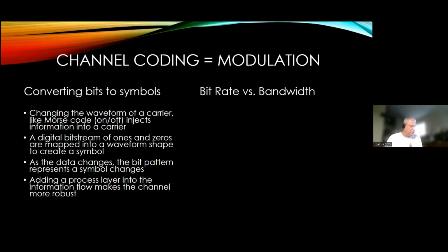I'm pretty certain everybody understands the concept that when you transmit CW, the key signal is not a square wave. Because if it is, you're going to make key clicks. And there's a guy that wrote this website. He's got a great explanation. Doesn't take a lot of math. It's easy to understand. It's how the slope changes from going from full off to full on.